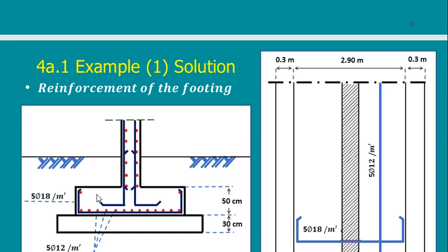Maybe a little bit protruding from the wall, like the case here. This is the column. It took the thickness of the wall and extended a little bit outside. This is acceptable. But to have the column alone, maybe 2 meters inside the room, it is not acceptable, because you need clear space in each room.